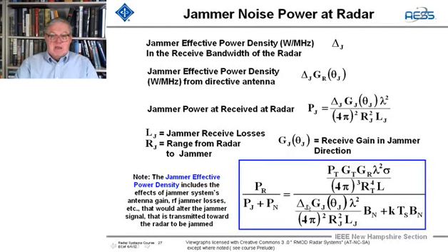So we have our radar equation, the same top part, but instead of on the bottom just having K, T sub S, B sub N up here, we have to add in these factors to calculate this ratio. Now what does it say? It says we want to have really low side lobes.